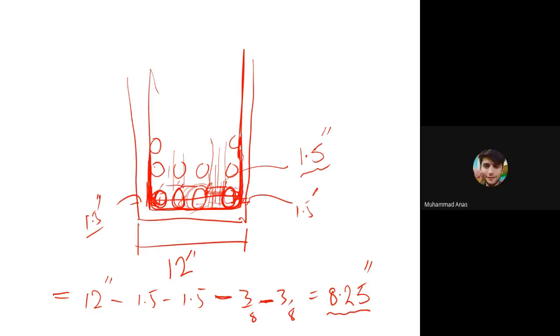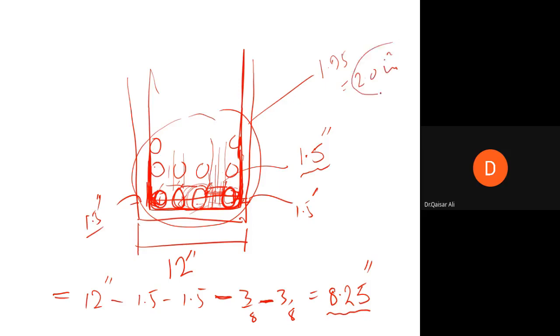नहीं, एक्सपेंसिव तो बिल्कुल नहीं होगा। उस वजह ये है, प्लीज एक मिनट सब्र करें, मैं इसका जवाब दे दूं ताकि ये कंसेप्ट आपको क्लियर हो जाए कि एक्सपेंसिव ही नहीं होगा। एक्सपेंसिव इसलिए नहीं होगा कि टोटल एरिया ऑफ स्टील जो आपका है ना, वो तो है 1.95, तो ये ज्यादा से ज्यादा 2 स्क्वायर इंच हो जाएगा। तो वेट तो 2 स्क्वायर इंच से निकलेगा, डायमीटर ऑफ द बार से तो वेट नहीं निकलेगा। अगर आप 10 बार नंबर 4 के इस्तेमाल करें और नंबर 6 के 5 बार इस्तेमाल करें, तो नंबर 6 के 5 बार उससे महंगे आपको पड़ेंगे, क्योंकि टोटल एरिया उसका बढ़ जाता है, वो 2.2 स्क्वायर इंच होगा, ये 2 स्क्वायर इंच है। वेट तो एरिया से निकलेगा ना, डायमीटर ऑफ द बार पे तो डिपेंड नहीं करेगा। तो ये कंसेप्ट आपका क्लियर होना चाहिए कि प्रोजेक्ट अनइकोनॉमिकल तो नहीं होगा। ओके, ये पॉइंट क्लियर हो गया कि अनइकोनॉमिकल नहीं होगा।